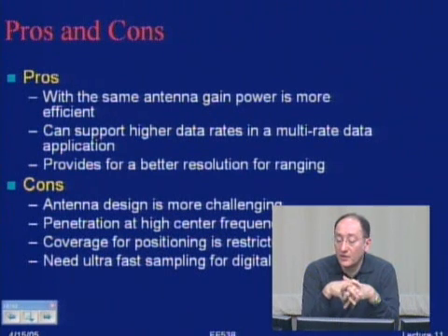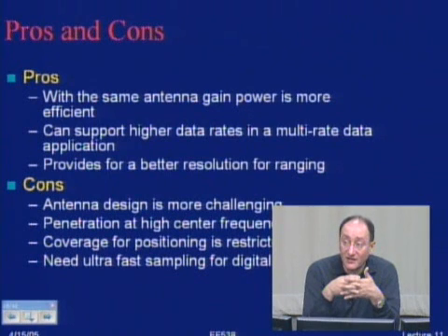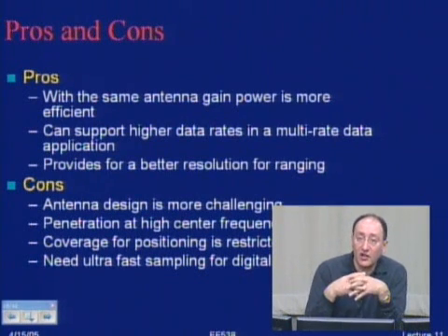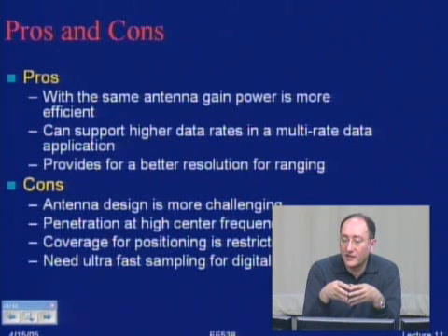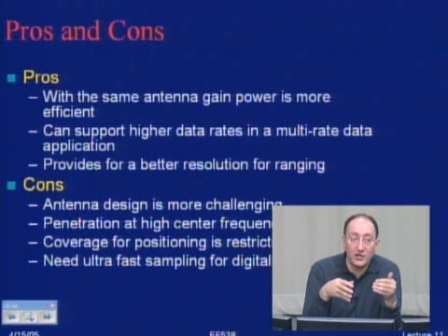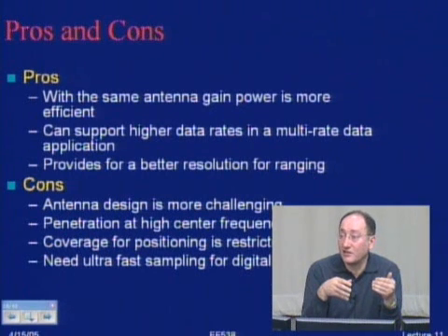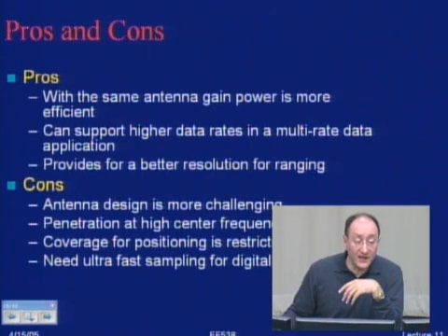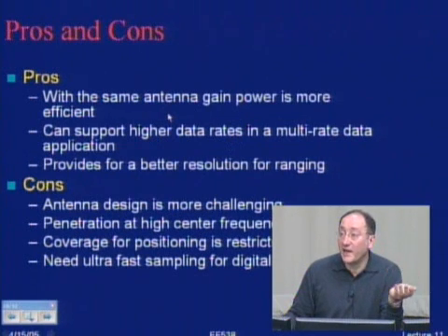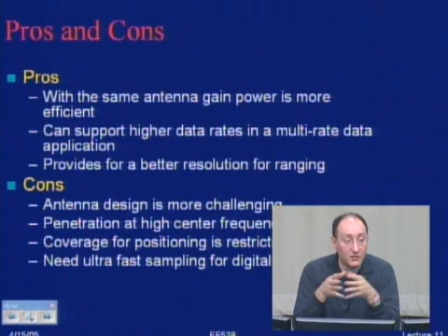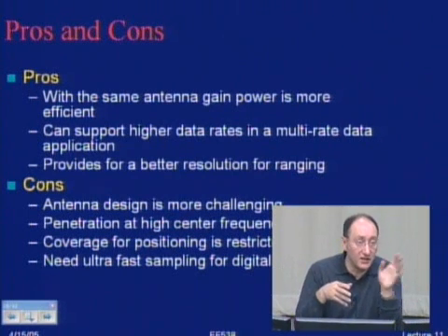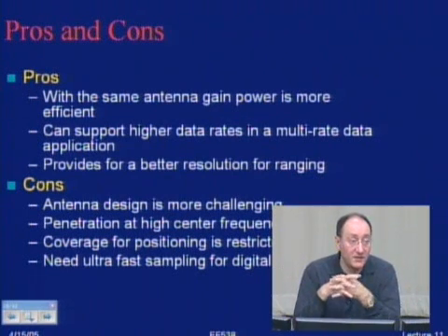If you go to a non-multipath environment, with additive noise, in an additive noise channel there is also the Cramer-Rao bound, which shows that as you increase your bandwidth, you have more accurate positioning. So these are beautiful advantages of going to wider bandwidths. And ultra-wideband we refer to as around gigahertz bandwidth.